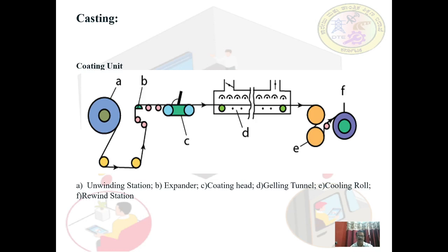Next type of molding is foaming. By adding physical or chemical blowing agents to a polymer, foams are generated. Physical blowing agents include gases and low boiling compounds, whereas chemical blowing agents generally are gas releasing compounds.